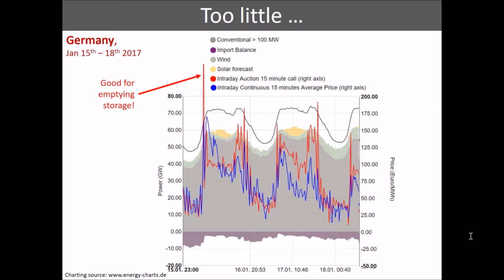We've got time of high demand, we've got very little wind, so what we've had to do is turn up more of our conventional plants, and in particular we've had to turn up some of our peaking plants, which are going to be very expensive to run, and also because in the previous chart, and other times when we've got lots of renewables in the system, which we take first, they're not being required to run. When we call them up, they know that they're kind of a last resort, so the prices tend to go very high. So that's two examples within a short period of time where lack of flexibility has caused economic issues, so negative pricing and real spikes in peak pricing.